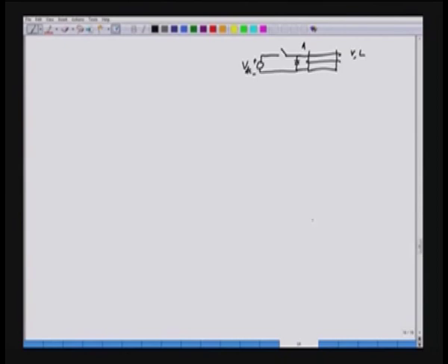When we apply this voltage called VDC, the current i flows through the winding. So, we can write down the equation that V is equal to the resistance drop plus N d phi by dt, where phi is the flux linkage in the winding.